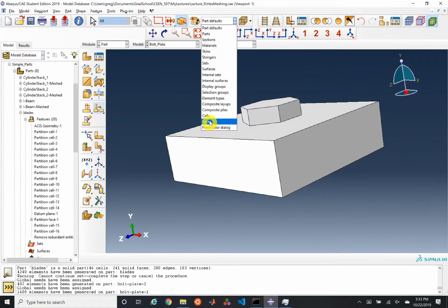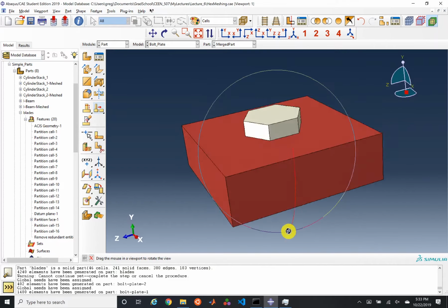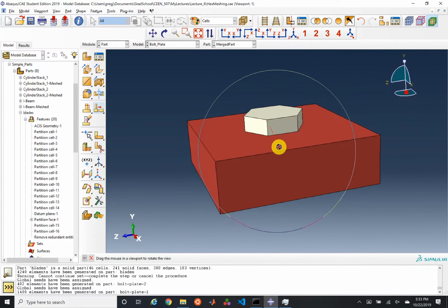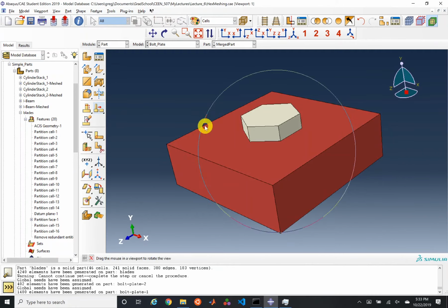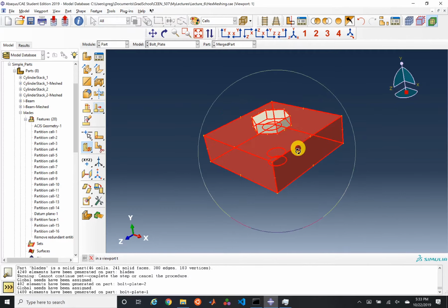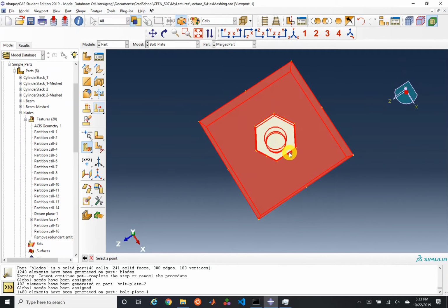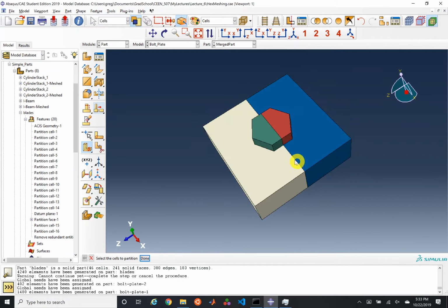And I can see that I've got multiple cells, I suppose, because I had previously defined this bolt to be two cells. And now here we could go ahead and mesh. I could choose to mesh this entire geometry with, say, a cut down this plane.